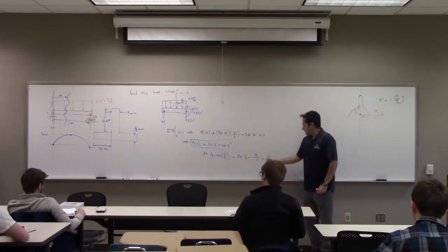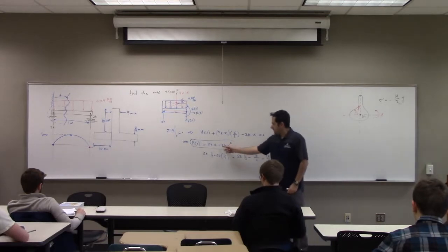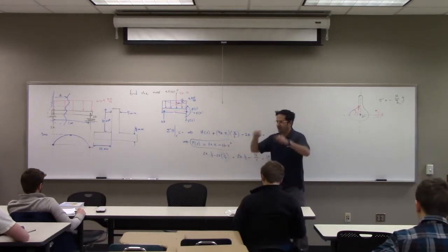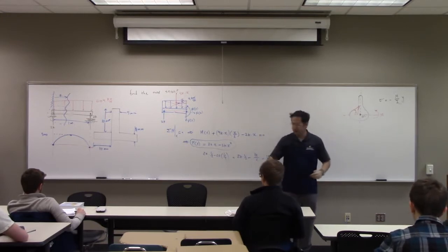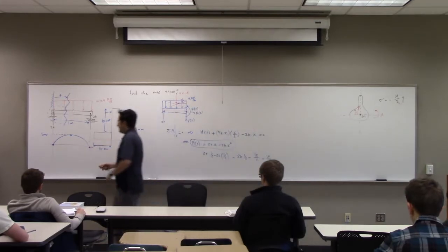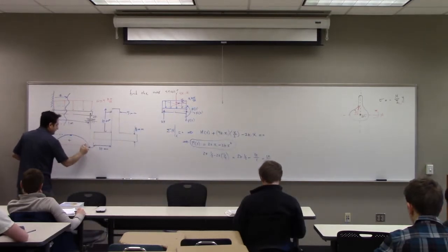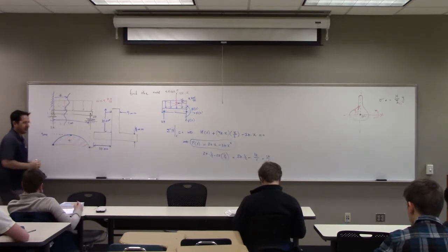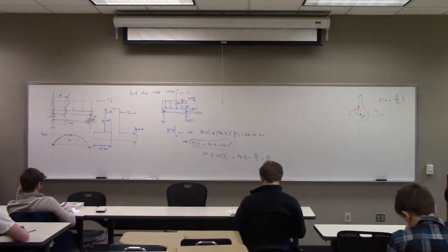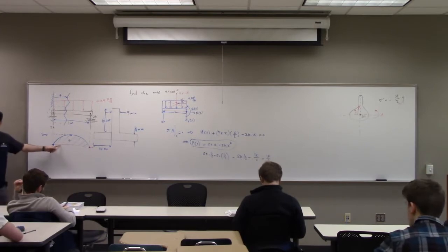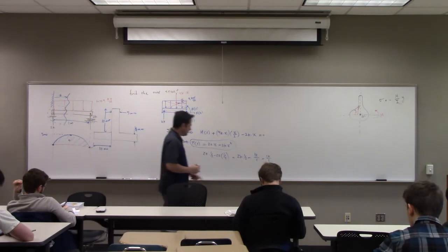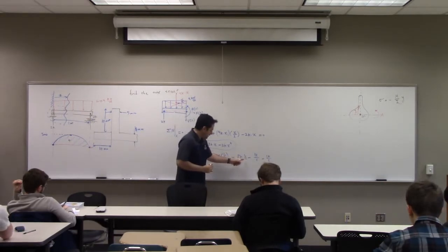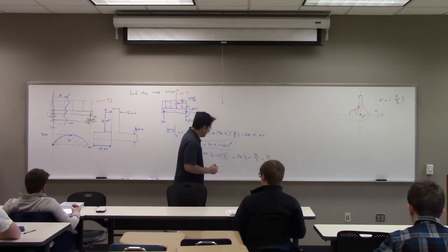Or we can say the coefficient of the second order term is negative. That means the convexity is down. The direction of the parabola is down, so that makes sense with this. So this is my positive moment diagram. Now you tell me where is the maximum moment? At the exact middle. And the value is equal to 500, according to that equation. Let's double check this: 1K minus 1 over 2, 1K, 500.